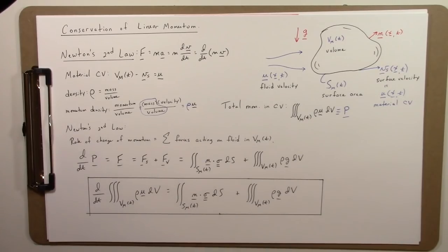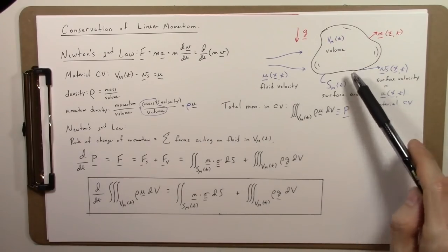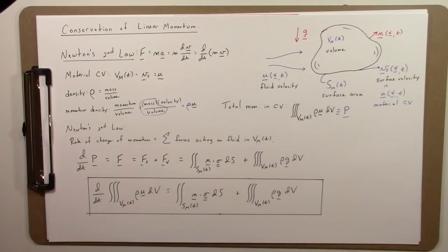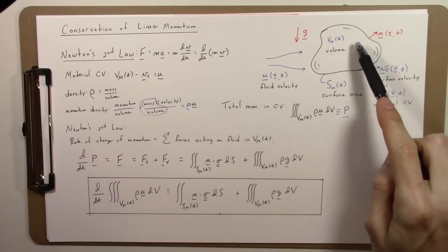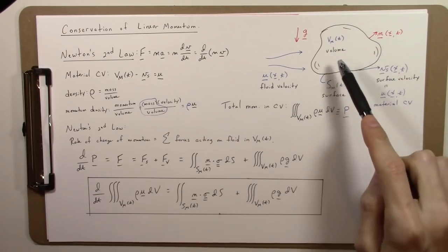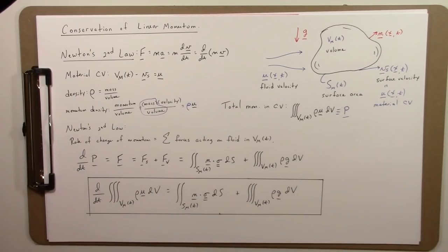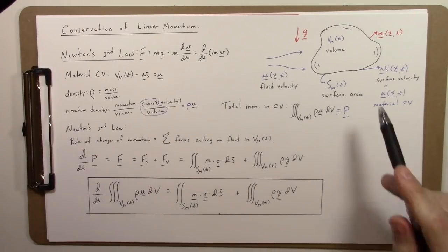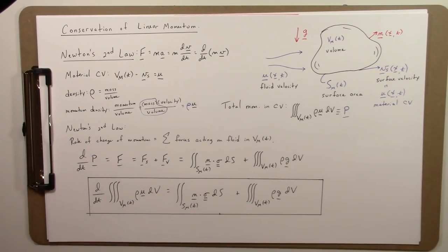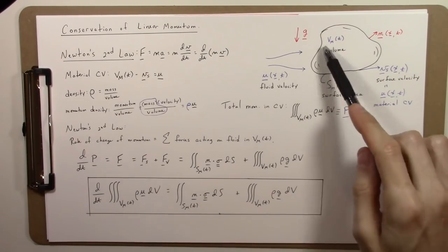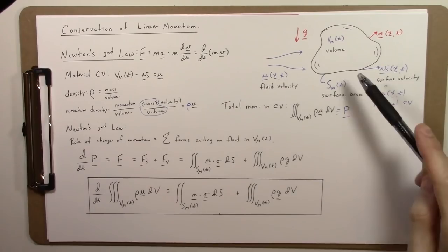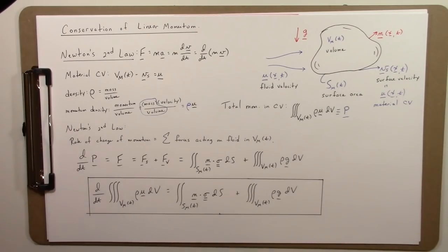Because the point x is arbitrary, and because the actual shape of the control volume is also arbitrary, the only way this combined volume integral will be 0 for any choice of position in this volume and for any choice of control volume is if the integrand vanishes at every point within the fluid domain. So we can then prove the integrand of that volume integral must vanish at every point in order for the integral to be 0 regardless of what point or control volume we choose.